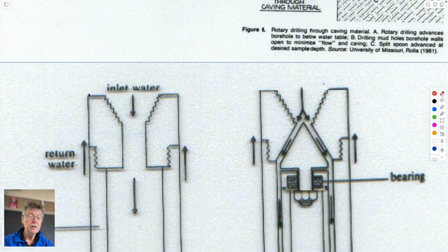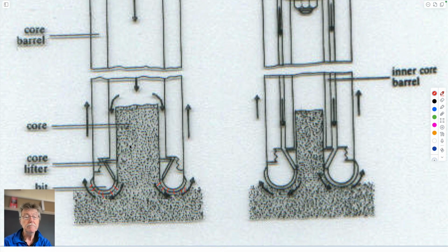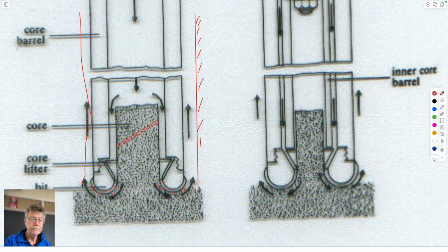Typically you don't collect them because they're no use, they're just flour, and you're counting on the fact that you get some good quality core here. Usually there are fractures in the core, so you don't get an intact piece of core which is 2 meters long or 3 meters long that hasn't broken here and maybe rotated against itself in the core holder. And so this here, I guess this would be the side of the borehole that you're making, all the way down here. And so this return fluid would be coming up inside the borehole between the borehole and the drill steel.